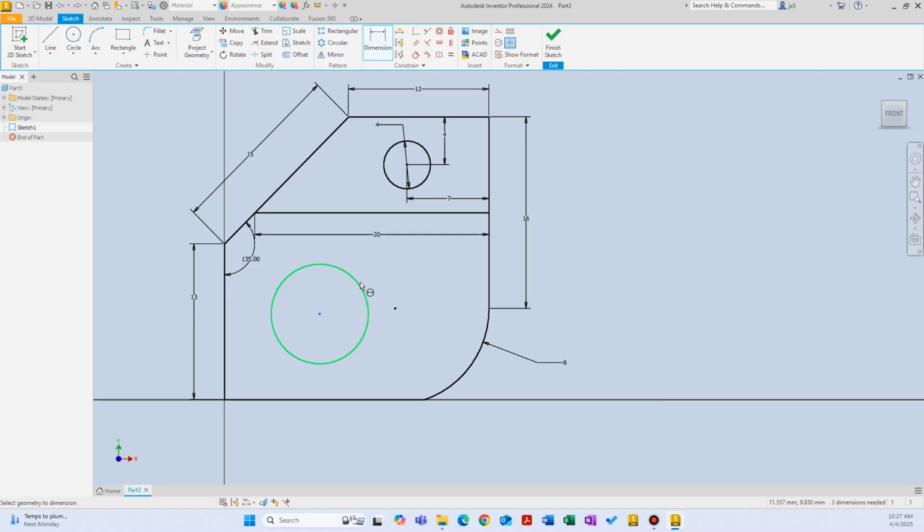But if you want to assign a diameter, just know that you don't have to use diameter as your dimensioning unit. You can always assign a radius. So as you click on the circle, you're creating a diameter, but before you create it, you can right click and see that dimension type is active in your right click menu. Now diameter is active, but you can click on radius and use radius to dimension the circle. So let's say this is a 4 millimeter radius circle.